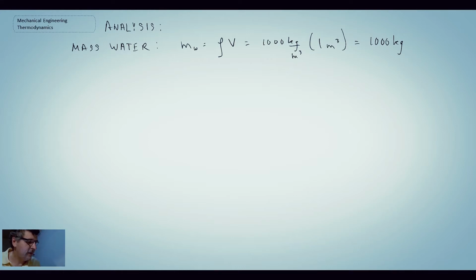So we want to figure out how long do we have to have the heating system on during the 10-hour night. We know the heat loss, we know the temperature of the water at the beginning, we know how much energy comes in through our electric resistance heater. This sounds like the first law. So let's apply the first law. And this is going to be the first law applied to a fixed mass or closed system.